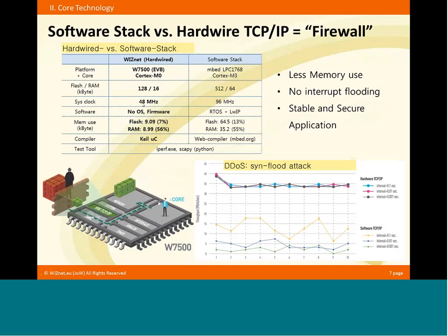And we have made a small demo application, and this is not using any kind of interrupts or so-named operating system. So it's a straightforward firmware. Without operating system, you have an internet application. And for that small application, we occupy just 9K of flash and 9K of RAM.